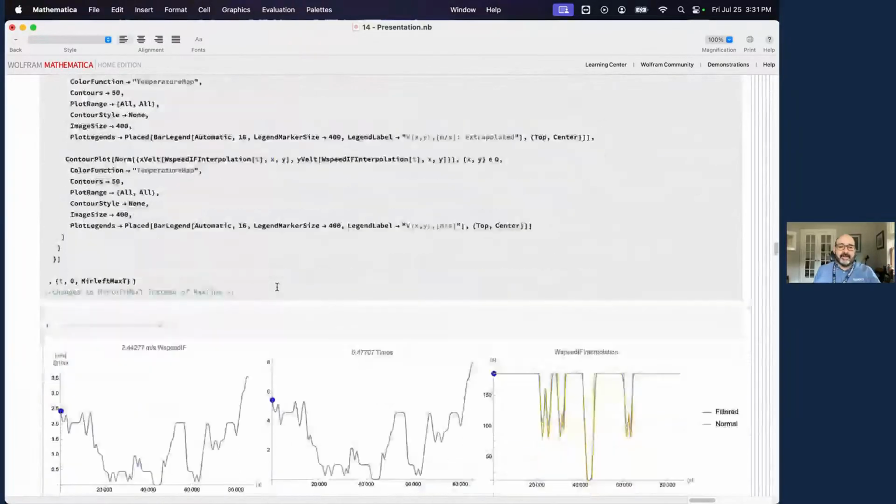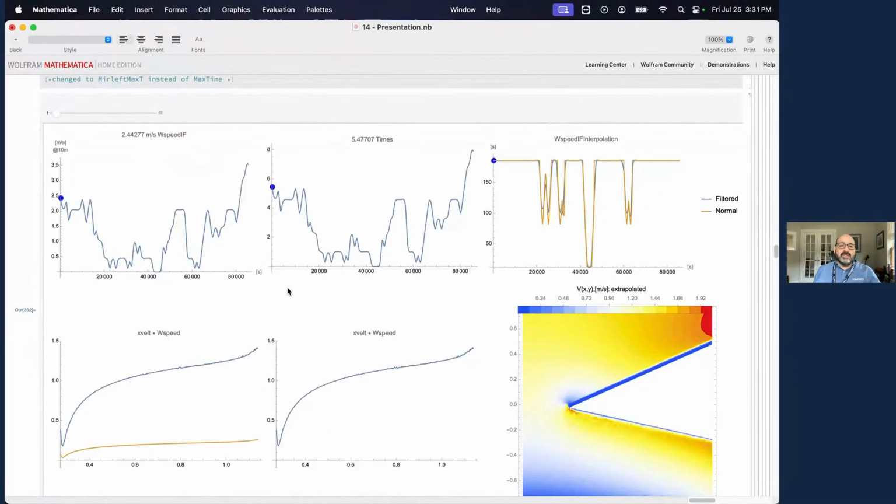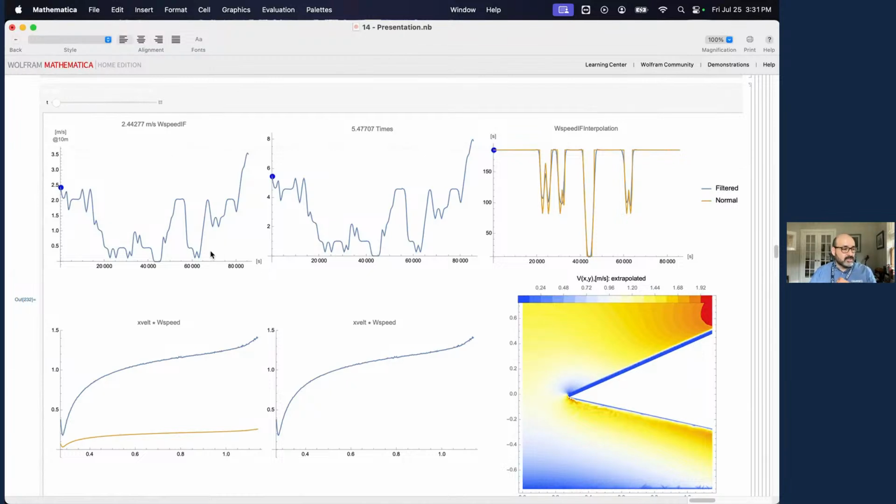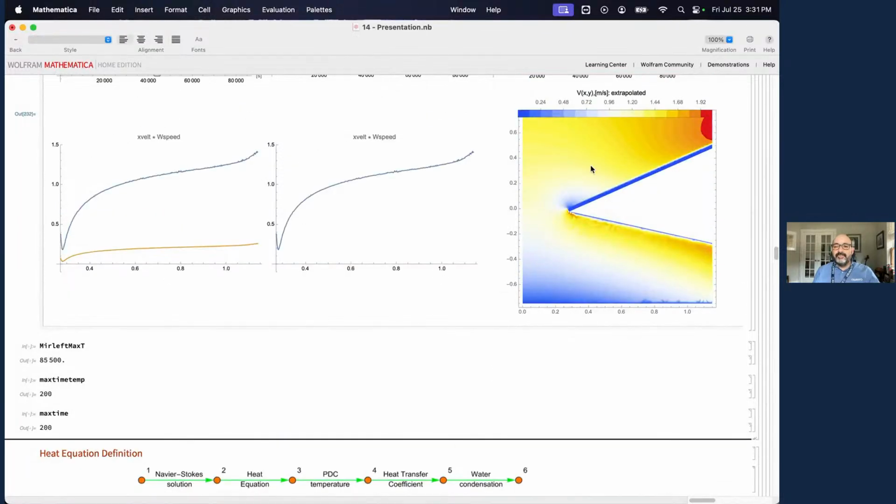So wind interpolation, so I'm creating all my equations, and you can see here, I just take my extrapolation. What I was telling you about, I was able to calculate the Navier-Stokes equations for 1 meter per second, but the data comes in at more than 1 meter per second, up to 5 or 10 meters per second. So now I need to extrapolate that. So I generate an extrapolation function, and then you have it. So basically now you are able to get any result of the Navier-Stokes equation at other velocities, right? You cannot extrapolate too much, right? You need to be careful, because if I say that the actual wind conditions were 100 meters per second, obviously this is not going to be correct. But in the small range, you could use these linearization techniques that I'm describing.